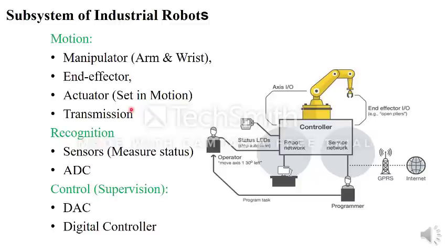Electrical actuators are currently the most widely used nowadays because they give precision control and are easily controllable. Maintenance is very low when compared to hydraulic and pneumatic. So nowadays most of the robots are going with electrical actuators, where BLDC motors are highly used because of higher efficiency. Brushless DC motors are the technology that is going on in electrical actuators.